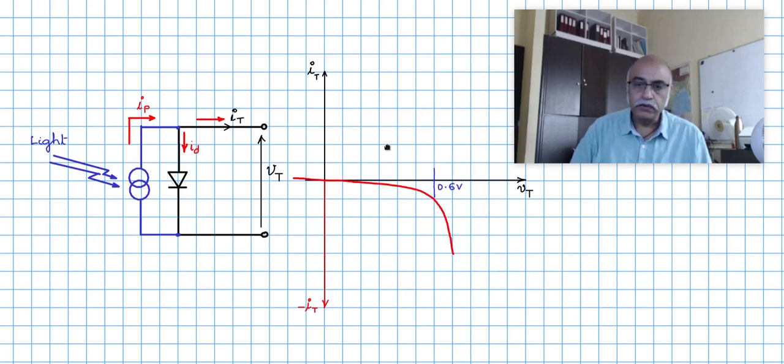Because there is a positive current going through the terminal, if an external load is connected across the terminal, the characteristics, because ID is going to flow through this one, this is the ID characteristic. So there is a DC shift; this whole characteristic will shift up because of the excess photon current flowing through the external terminals.